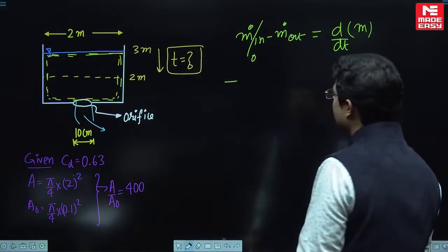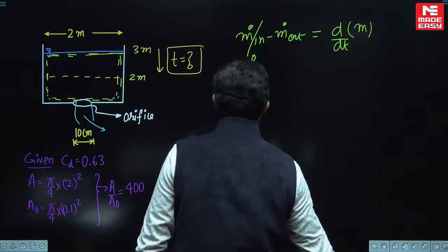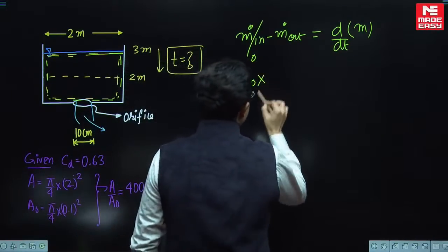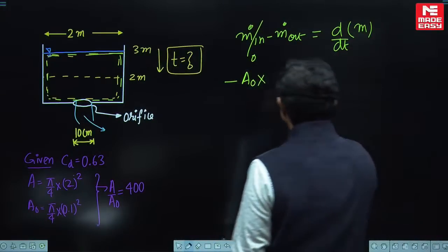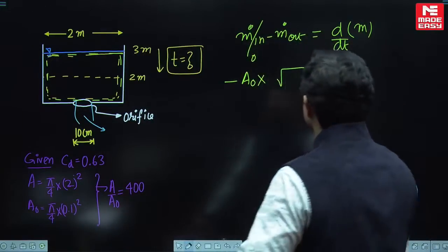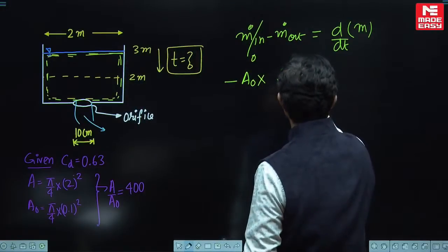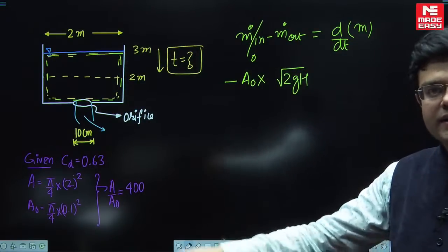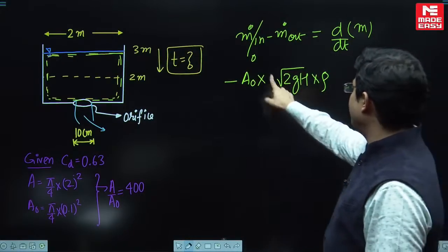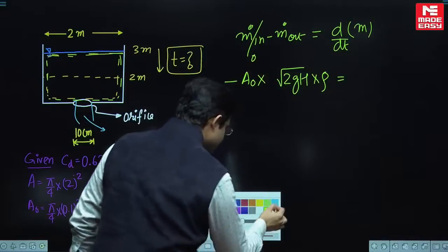What is M dot out? M dot out is going to be the discharge. Discharge will be the area through which it is getting out, which is the orifice. So orifice area I am taking as A naught, into the velocity with which it is coming out. M dot is rho AV, and the velocity will be under root of 2gh, whatever is the height, multiplied by density, rho AV, clear guys, is equal to...